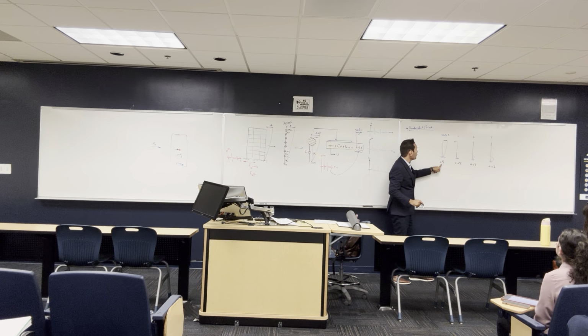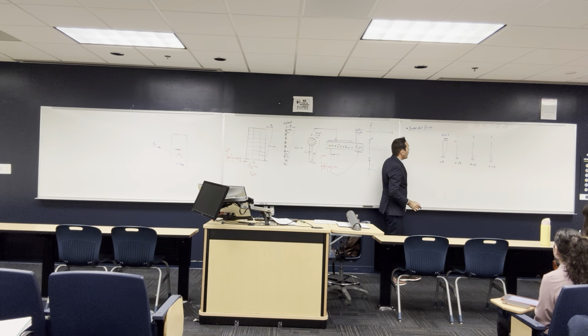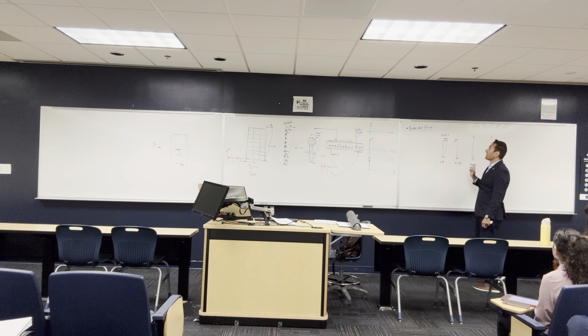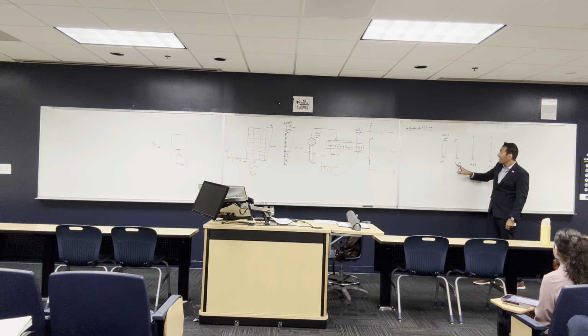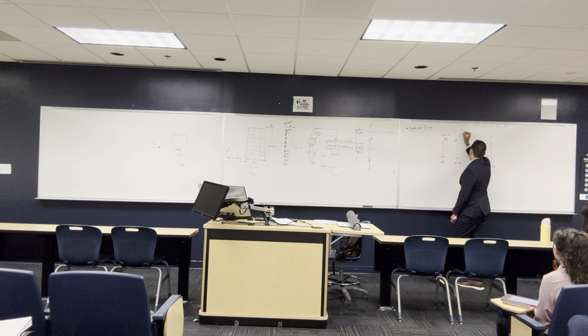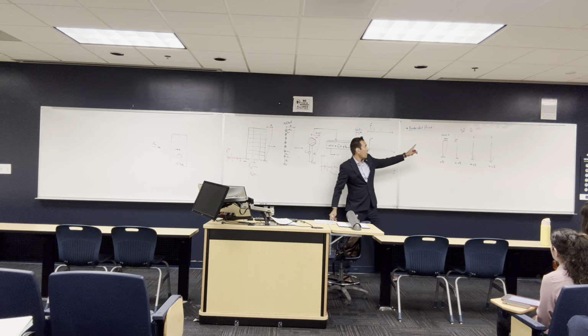So let's say this mode shape is going to make a displacement at the top of 5 centimeters. All right? And this one is going to make a displacement here of 3 centimeters. The thing is, you cannot say 5 minus 3. You need to multiply 5 by 0.9 and 3 by 0.05. So when you multiply 3 by 0.05, 3 times 5 over 100, it's going to give you 15 over 100, that means 0.15. Can you imagine 0.15 centimeter? You will barely be able to see it out of the 5 centimeters.